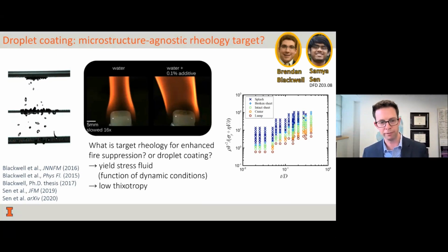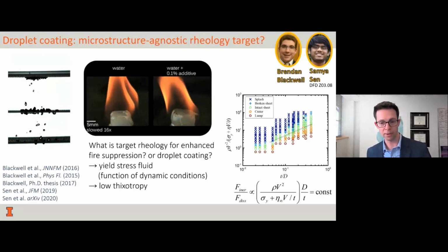If you create a fluid that has too much concentration, the yield stress is too high, it actually just gets stuck at the top. And there's some Goldilocks condition in between that allows you to impact and coat throughout. This is a high dimensional parameter space, like many of these droplet impact scenarios are in our fluid mechanics community. Using our typical approach in fluid mechanics, we asked, is there a way to identify a dimensionless group that can simplify and project the complexity into a single criteria?